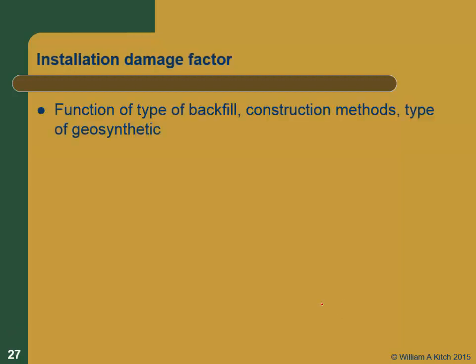Installation damage. This is going to be a function of the backfill, how you backfill, and the materials. This is one of the reasons that for the geosynthetics we're using plastics for the reinforcement, we limit ourselves to 3/4 inch stuff, because with the bigger stuff you tend to get a lot more installation damage. With the steel, that's not such a big deal. So if you've got a situation where you're going to be having gravel and very large reinforced soil materials, then you want to be using steel.